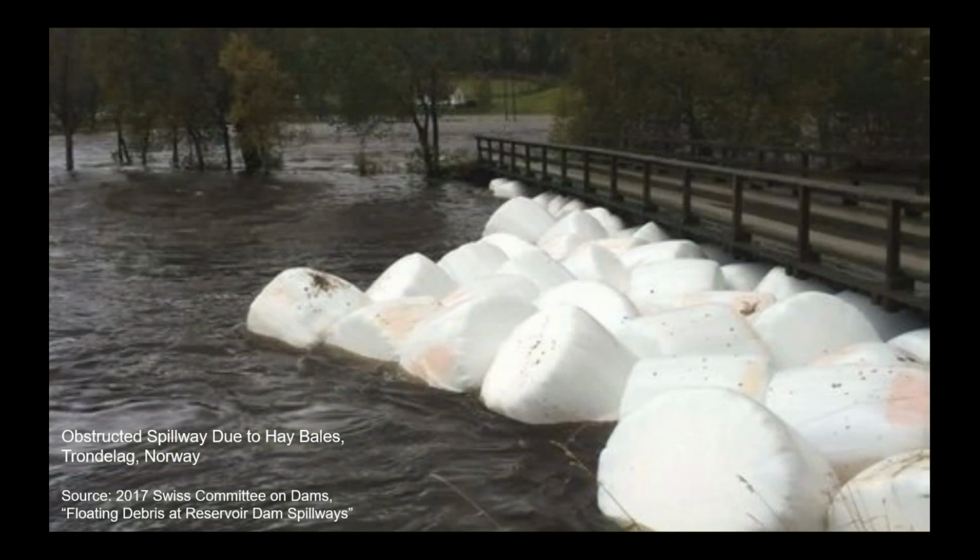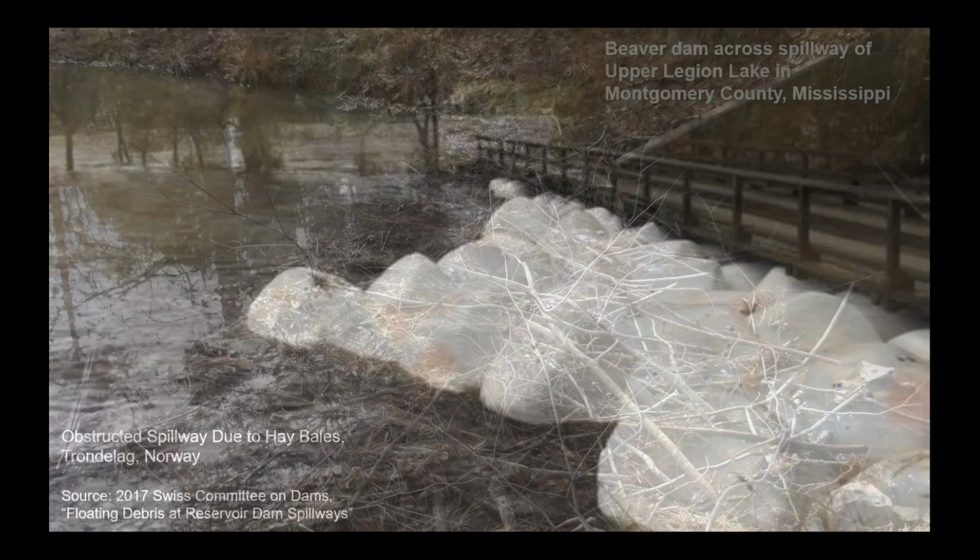And then the same thing happened at that project with the auxiliary spillway. It clogged part of the auxiliary spillway and forced the water to one side and caused it to erode. Here's another example of the hay bales, only these are wrapped with white plastic, so they look like marshmallows. And these are really prone to floating, and you can see how they obstructed this spillway, especially because it had a bridge across the top, which caused them all to accumulate.